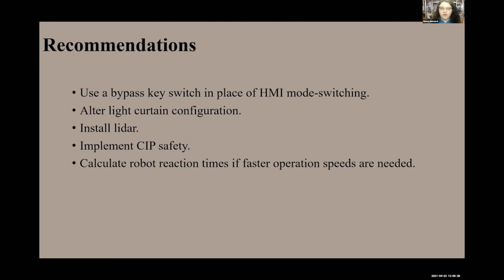Next slide, please. Some recommendations for the client in the future are the installation of a bypass key switch in place of the HMI to better meet safety regulations. Another is to alter the light curtains to work with other capstone projects. For example, the Robotino project, where triggering a mute sensor at the appropriate time will allow the Robotinos to access through the light curtains without tripping the safety system. Another thing that can be installed is the LiDAR for extra safety, and this will prevent the light curtains from being reset while a person may still be in the robot cell.